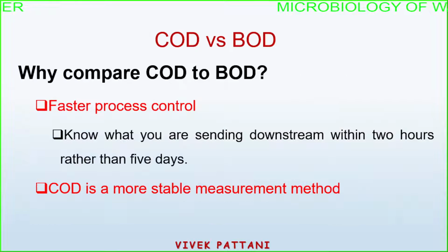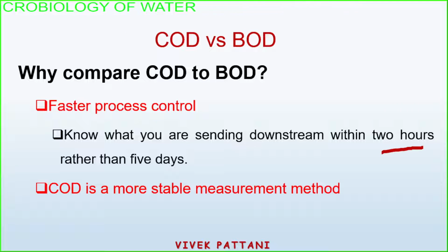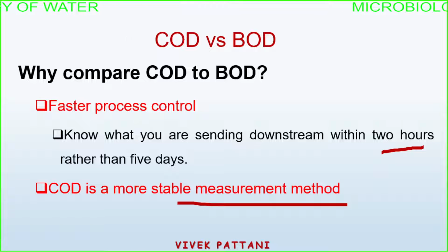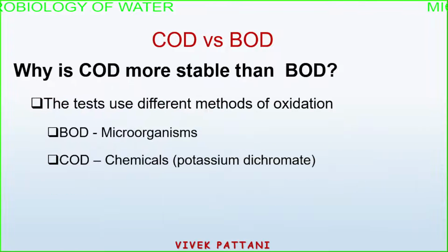Now, what are the differences between COD and BOD? COD is firstly a faster process, it is done within 2 hours, and it is a stable method. Okay, whereas BOD takes almost 5 days. BOD takes almost 5 days.